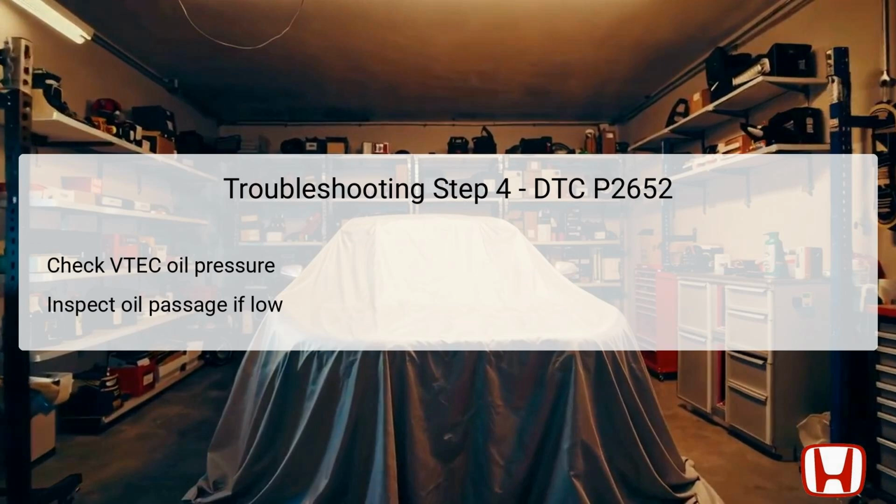Conversely, if the oil pressure is inadequate, you need to inspect the VTEC system oil passage for obstructions. Cleaning or repair of the passage may be necessary before proceeding. During the fifth step for DTC P2652, the focus shifts to verifying the integrity of the wiring that connects the PCM to the rocker arm oil pressure switch.